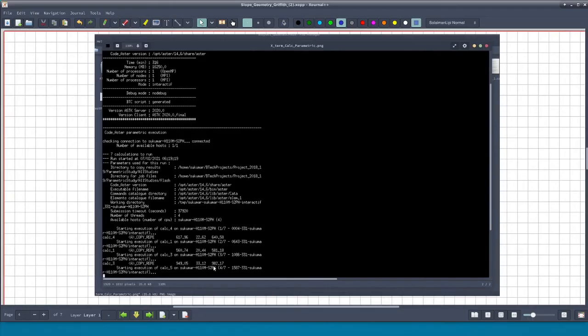These are the times necessary in seconds for every calculation, and you can see that these calculations take quite a bit of time. As our strength reduction factor approaches the actual factor of safety, this time necessary increases because the convergence becomes slower and slower. Therefore, many times in slope stability analysis we may have to repeat the analysis with some new selected factors of safety or SRFs so that convergence is achieved.